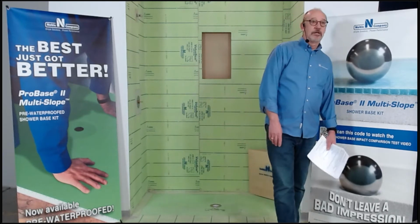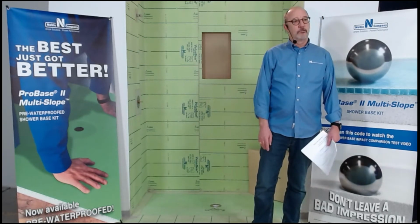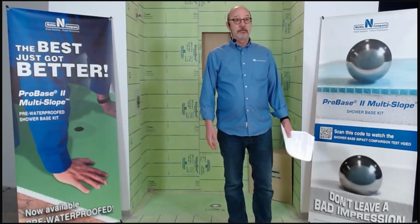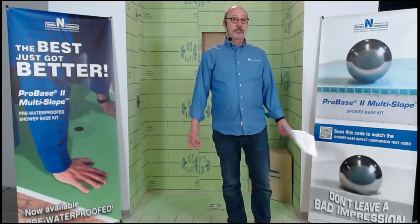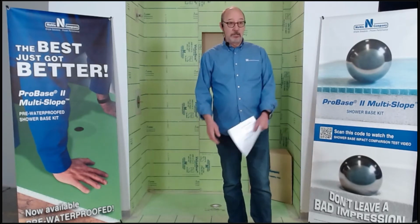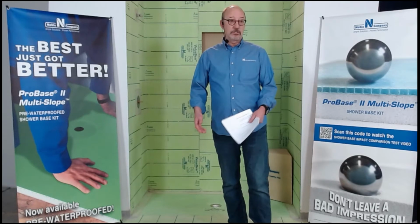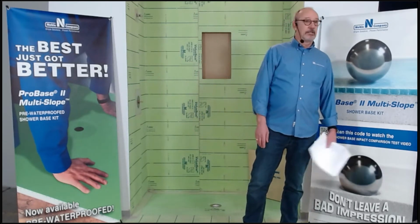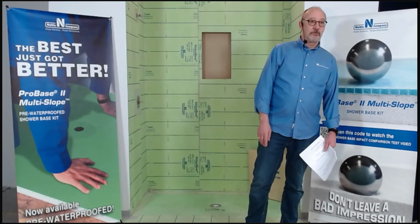Obviously, some considerations are, what is the substrate that we are dealing with? Is it wood framed? What are the joist spacing? 16, 19.2, 24 inch? What is the length of the unsupported span? Is it a beam, sawn lumber, 8 inch, 10 inch, 12 inch? What are we dealing with? Does the deflection meet the industry guidelines of L/360 or L/720 for natural stone?